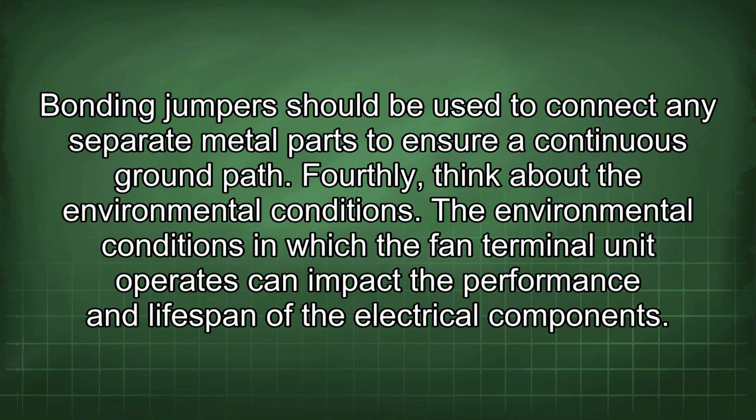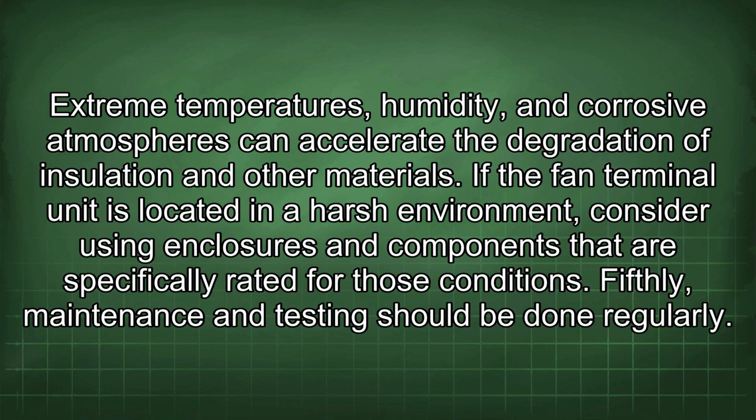Fourthly, think about the environmental conditions. The environmental conditions in which the fan terminal unit operates can impact the performance and lifespan of the electrical components. Extreme temperatures, humidity, and corrosive atmospheres can accelerate the degradation of insulation and other materials. If the fan terminal unit is located in a harsh environment, consider using enclosures and components that are specifically rated for those conditions.